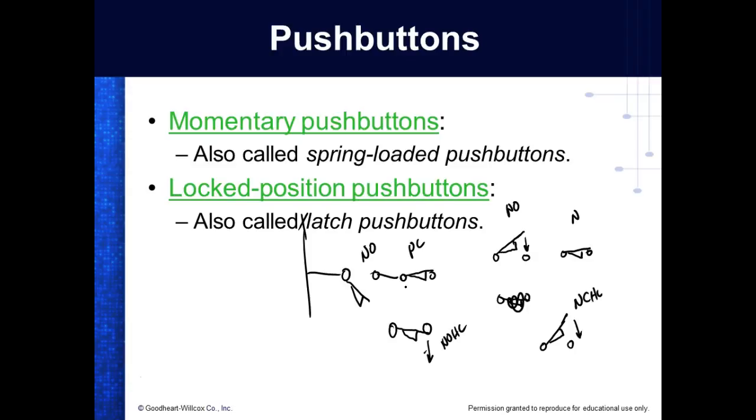So that relay that I passed around is a 2-pole relay. This is called a 2-pole single throw relay. There are 2 contacts in here, so it's 2 switches, and each one of them only has one position. We can either close it or we can open it, right? Now if I come over here and connect these together, then they're going to act like a single pole double throw. So we can make a relay.